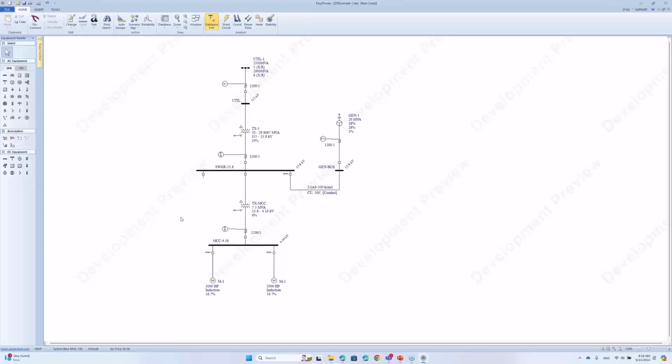So our purpose here is to make sure that for a simple network, which is solely sourced by the utility, we are expecting the arc flash results at a bus in short circuit focus to be consistent with the arc flash results obtained in dynamic stability focus, because there is no dynamics involved anywhere in my current system after I open these breakers, right?